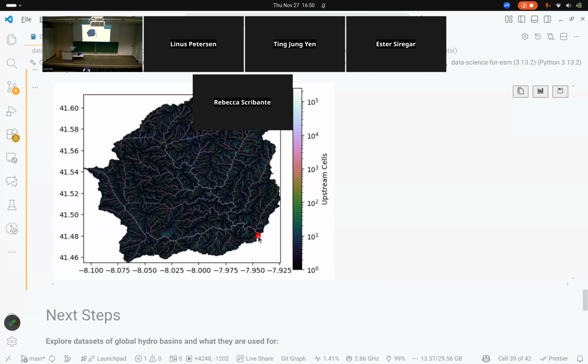And then we can look at the weather data for this area, which might come in a different raster at a different resolution, and from that build up how much water we have, and typically that is done at a daily rate. So unlike for wind and solar, where we typically have hourly resolution, we would look here at daily flow rates.